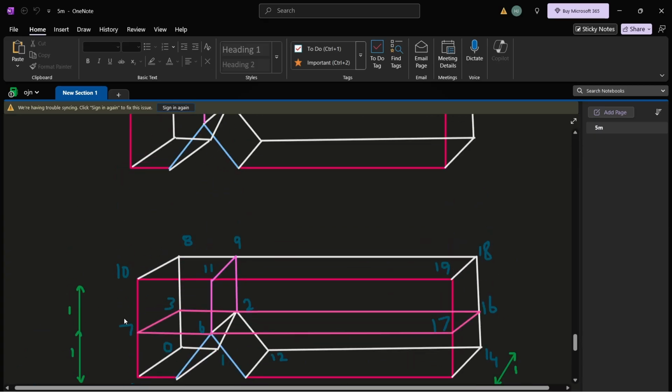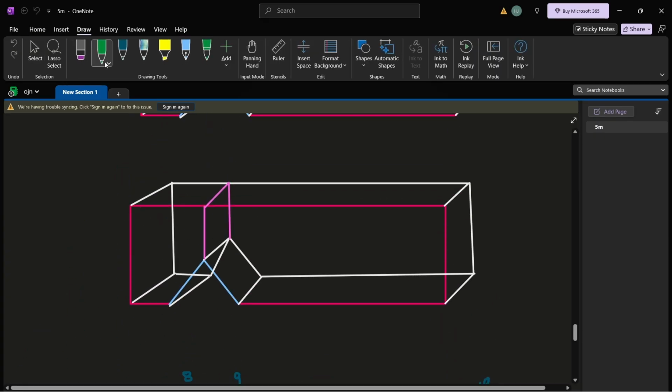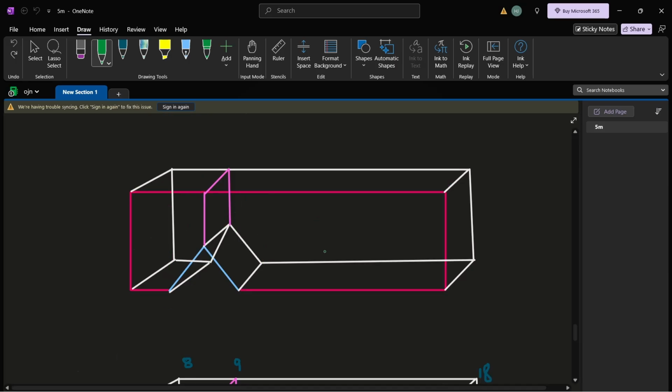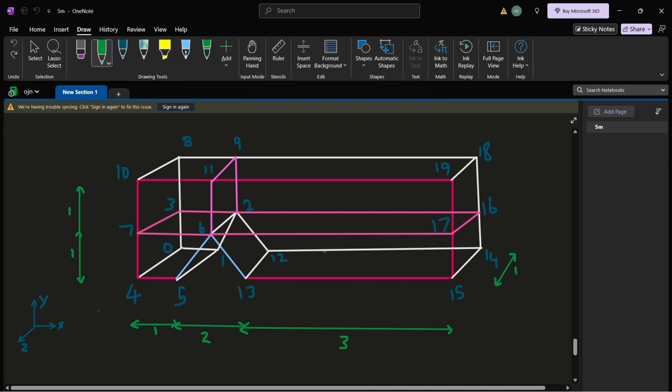But if you see in the previous video, I split everything vertically, something like this for all the blocks. So the blocks would have looked something like this. We had one block, second block, the third and the fourth. But I have also mentioned that this is not a very optimal way to mesh this geometry. So here I am with the optimal method, which is splitting it horizontally instead of vertically.